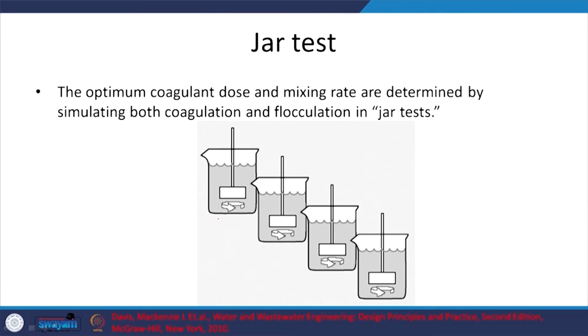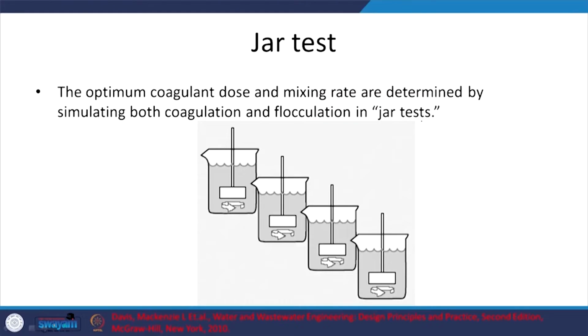So it's simple. I'm going to take the sample, and here what are the aspects of interest? We remember that pH plays a role, because depending on the pH you can have precipitation occurring, or you can have different charge out there. So you can vary two primary variables. One is the charge, indirectly by the pH, and also the coagulant dose. These are the two aspects you will check while conducting these jar tests in the lab.